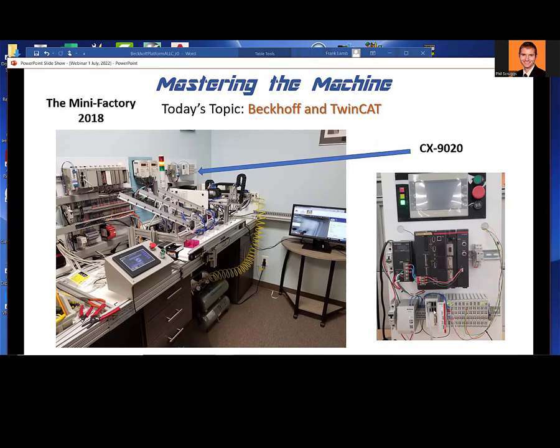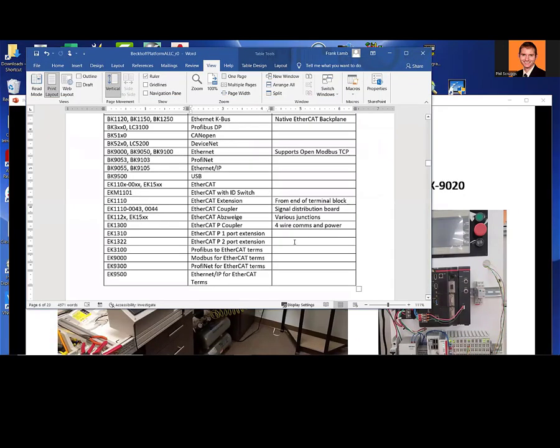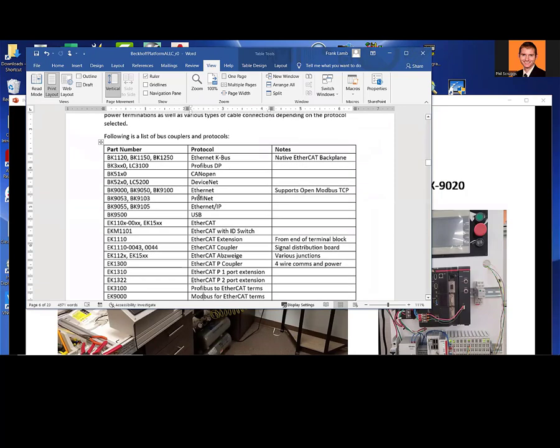And I could go out this port here on EtherCAT and connect to a bus coupler also running EtherCAT, so everything would be fast that way. A little bit faster than certainly TCP/IP would be, which is not something used for industrial protocols. So you can see all the bus couplers that they have listed here.